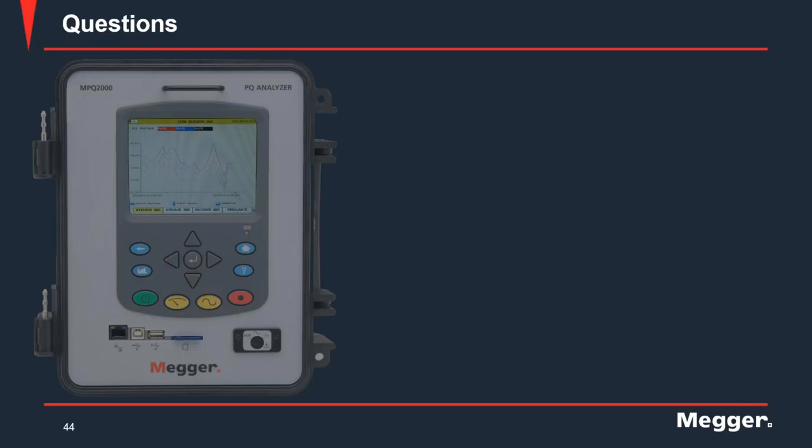All right. Next is over to Dinesh. Dinesh, can you review open delta connections for medium voltage connections? Okay, so yes, you can use the MPQ unit to do a study for an open delta connection. In the user's manual, there are multiple different configurations available, and open delta is one of those. You have to make your connections based upon the diagram, and it specifies how many voltmeters and ammeters you would need. So the answer is yes, you can review the open delta connections.